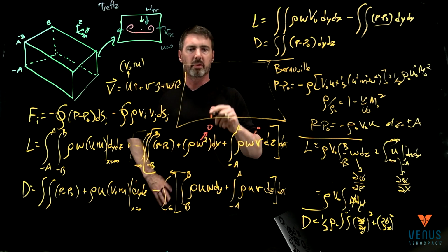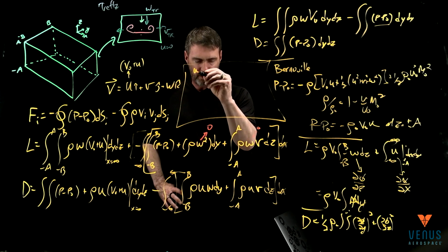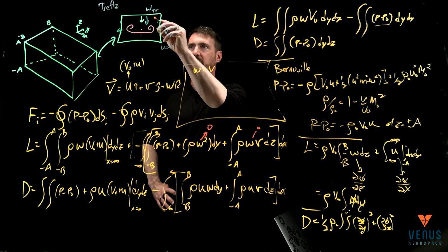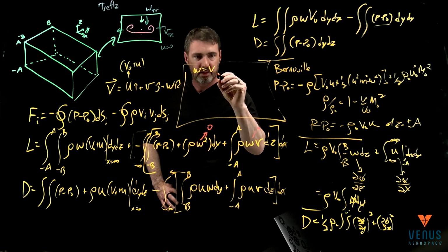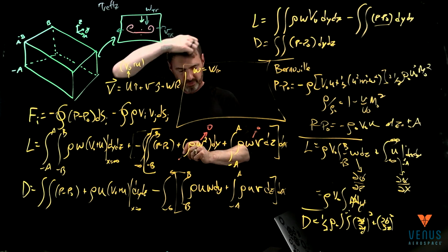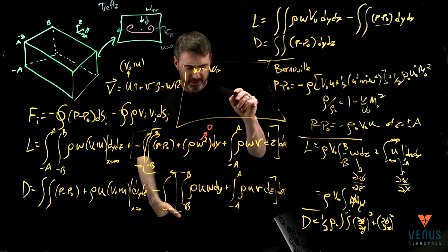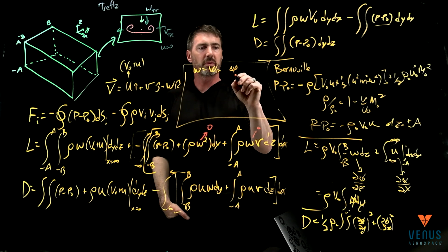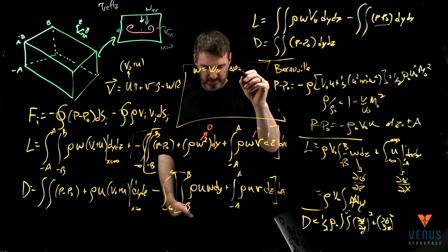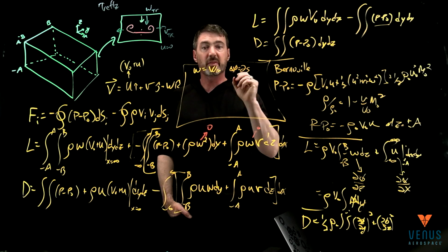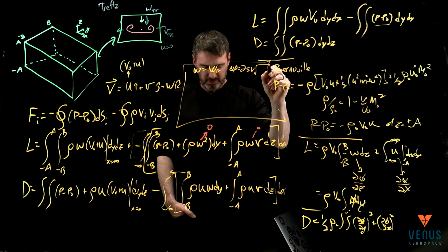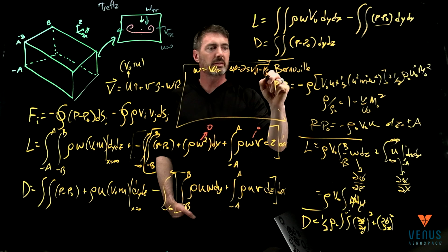Okay, so you can actually figure out that if we just say that on this exit plane this downwash is this velocity, you can write down the solution for the gradient of the velocity potential, and you can look in the book, but it's 2 times the span s, not the area s, times that velocity, square root of 1 minus y over s squared.